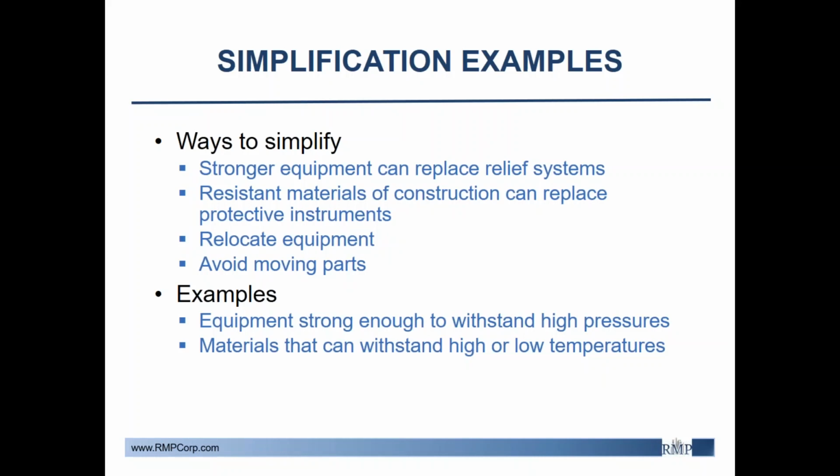One of the most important simplification techniques that can be easily overlooked is the relocation of equipment. Sometimes you'll find that, let's say, two tanks that interact with each other are located on completely opposite sides of a plant. That'll increase residence times and the need for complex valving along the way. Another example is if a tank that must be easily accessible by operators is located behind three other large tanks, requiring an operator to turn a bunch of corners before getting to it. This can increase operating procedure complexity as well as increase the time for an emergency response if needed.